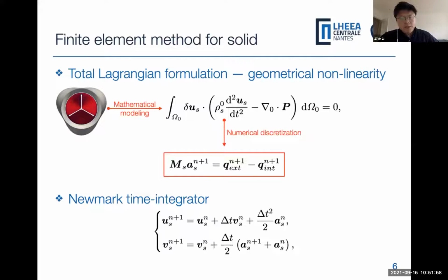In order to integrate the system in time, we choose a Newmark time integrator. Specifically, it is the explicit version of the numerical scheme, which is conditionally stable.